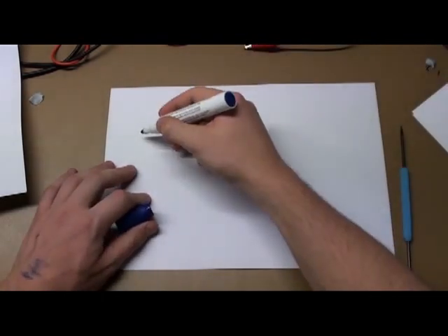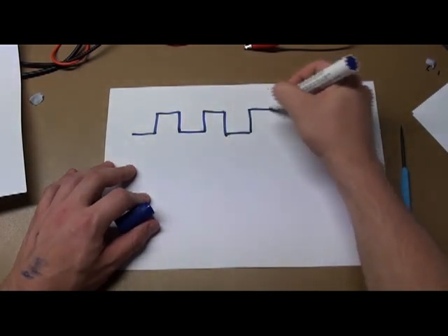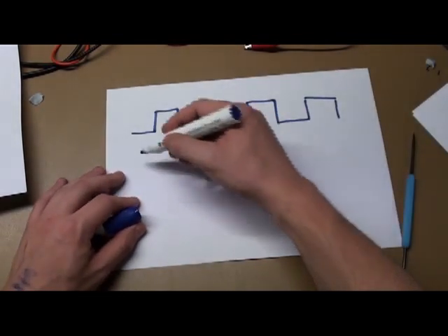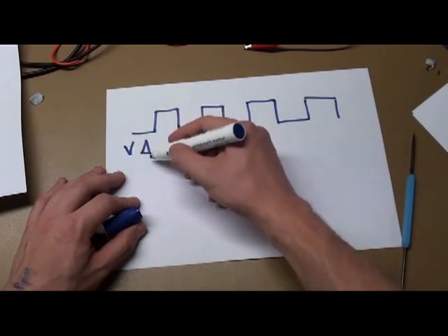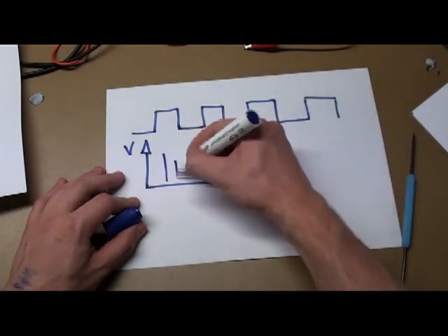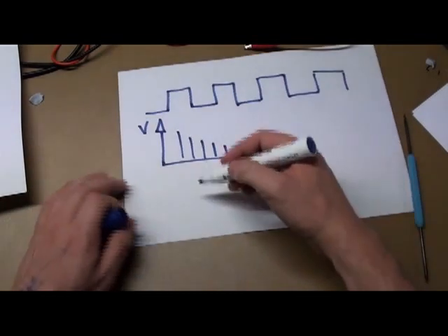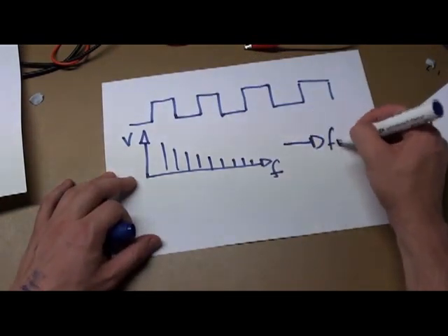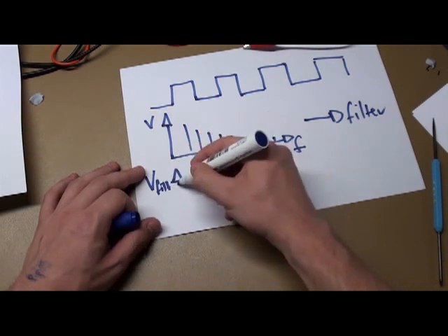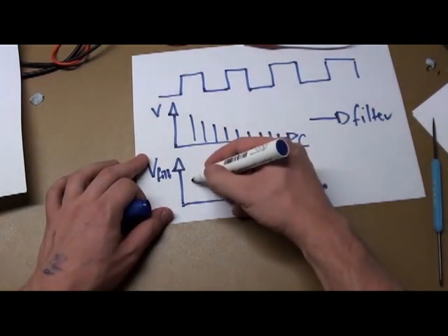But if you were to put our old friend the square wave in, which remember is infinity sine waves of different frequencies, if we were to have a very, very good filter, so volts, and this is frequency, if we have the frequencies in our square wave looking like this, and then we want to filter afterwards, then the signal might look like this.